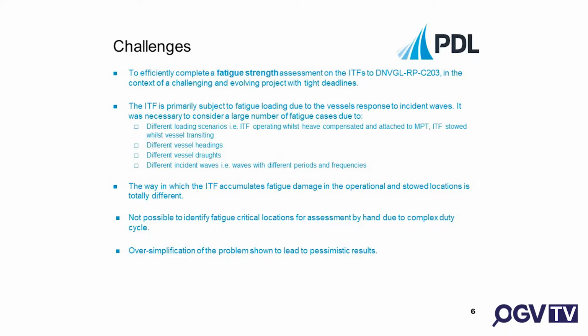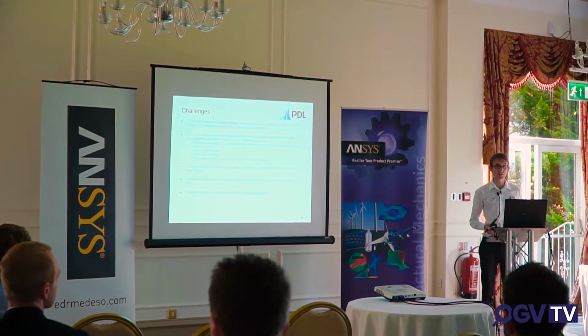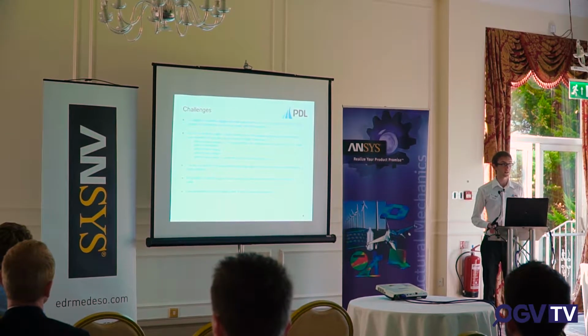And then the structure could obviously be operating. It could be slightly different types of operations, different riser hang-off loads, perhaps. And then obviously it can be stowed. Its stowed location is very, very different to its operational location, and it's loaded in a very different way when it's operating. It is truly a tension frame, mainly loaded in tension. When it is stowed, it is basically a tower, sea fastened somewhere else on the vessel.